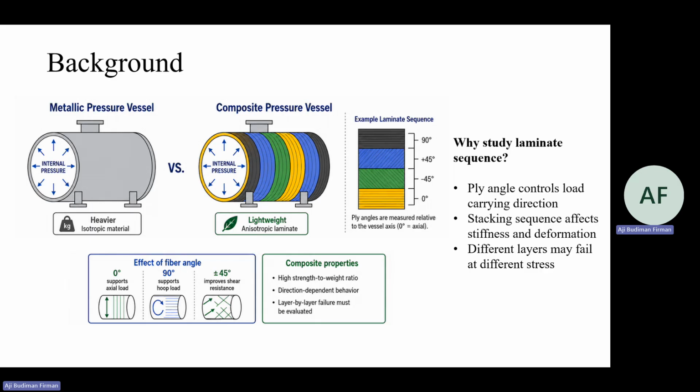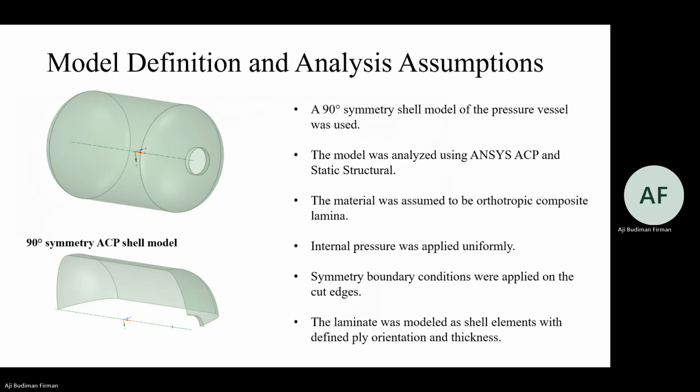This study evaluates how different ply orientations and stacking sequences affect total deformation and the Tsai-Wu failure index. Since the performance of the composite pressure vessel depends on the laminate arrangement, the model and assumptions must be clearly defined.